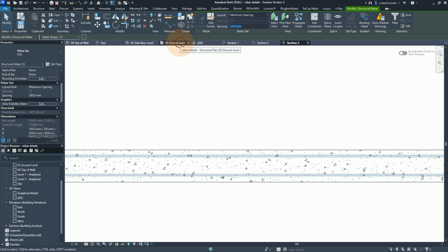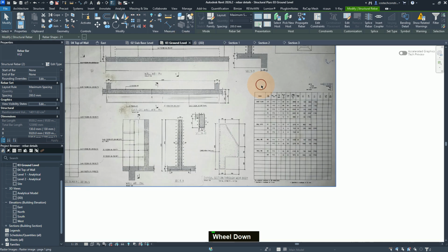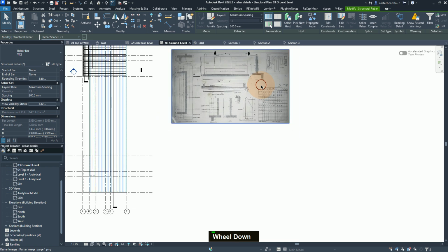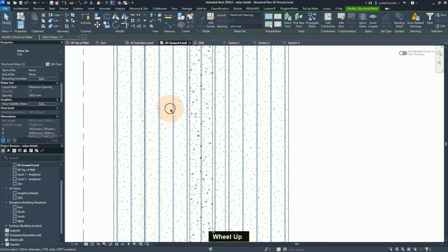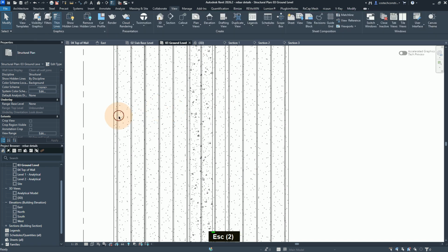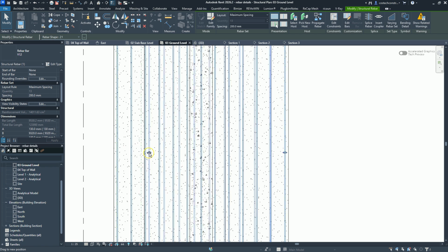So if we go to the ground level, we'll need to go and set the span. So we can zoom back at the drawing model here. I will hit escape. I can select this Rebar set. Now for this one, we can move it in up to somewhere here.